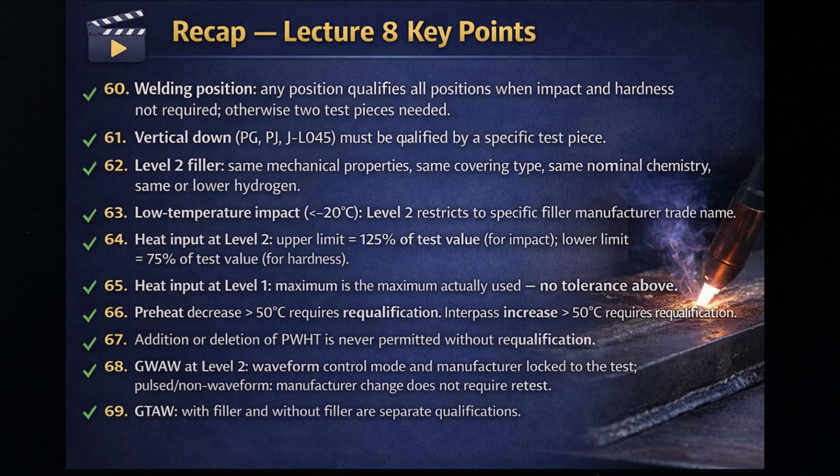66. Preheat decrease greater than 50 degrees Celsius requires requalification. Interpass increase greater than 50 degrees Celsius requires requalification. 67. Addition or deletion of PWHT is never permitted without requalification. 68.